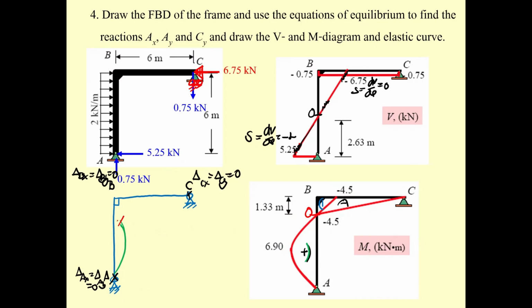The inflection point is very important for reinforced concrete because you are going to use it to place the reinforcement. Now, based on this kind of deformation, you will get a deformation like this one. This one must rotate due to rigidity, and following this deformation you will get a curve like this one.